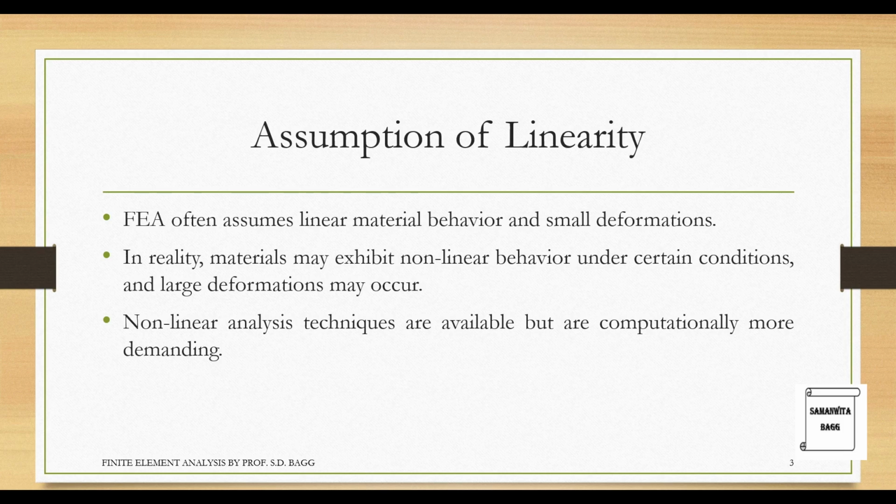Also, sometimes when you choose a material in ANSYS, you will assume that the material is linear and you do not incorporate the non-linear behavior into it. At that time also you will get an error in your solution. But there is a reason why we prefer using linear over non-linear. That is, non-linear analysis takes a lot of time to get the solution. It is possible that it can go up to half an hour at times, even with good processors.